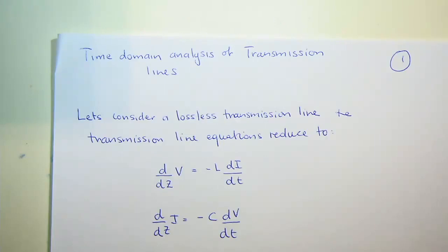It reflects back from the inputs of the power amplifier, travels back forward, and all of a sudden the voltage on that transmission line or that antenna that you're trying to excite in order to radiate energy isn't this nice sinusoid or nice square pulse that you expected. That could cause significant issues to a receiver that's trying to receive that signal, because all of a sudden it's not what it expects.